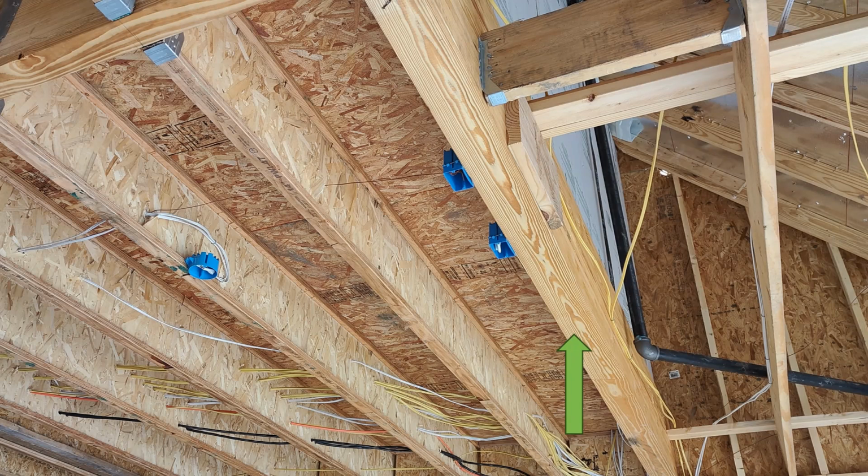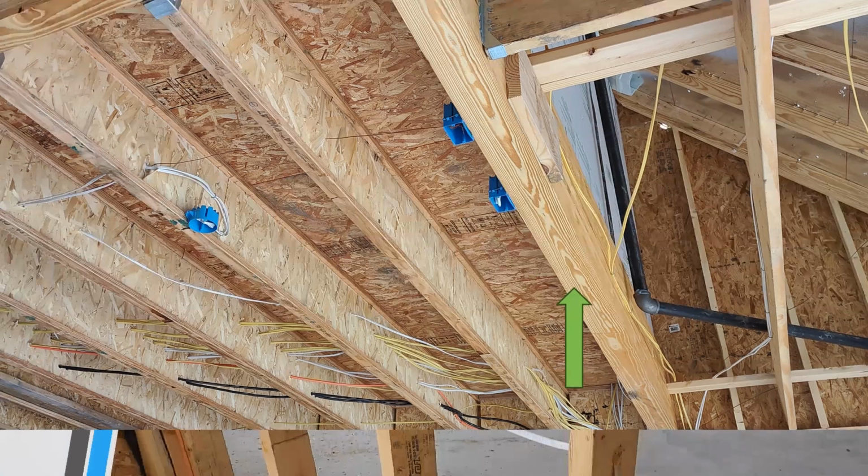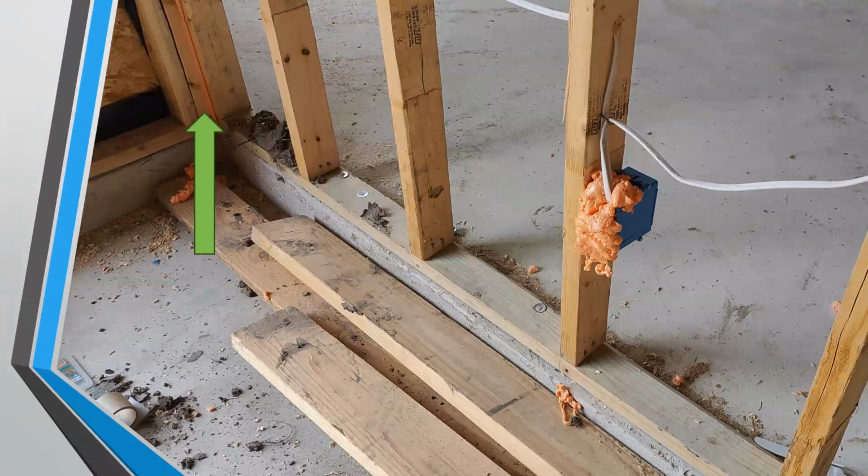And that air around that carpet's going up, but you have to replace it with something. It would not lift without a replacement of air. So there is air traveling into that cavity, being able to lift that carpet off the floor. OSB does have a tongue and groove lapping effect. Most of the time, those are not sealed. They're not glued. They're just allowed to be sealed together on their own, and they're not sealed in any other fashion, which leaves spaces for air movement through there. And so all of that should be self-contained and sealed off.